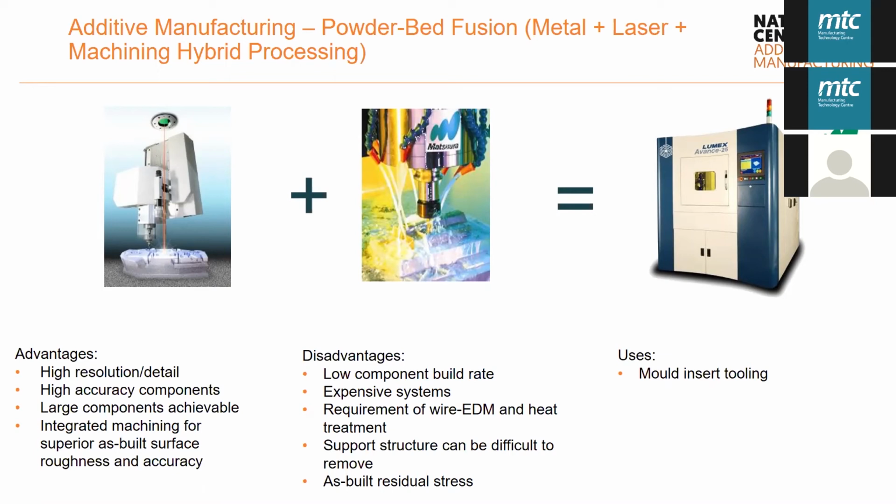It will allow you to have a much better as-built surface finish and as-built accuracy than your conventional LPBF component. But these systems can be quite expensive, and again, you do need to heat treat and wire EDM in some cases, and some support structures are still present because of the overhangs that you're potentially manufacturing.